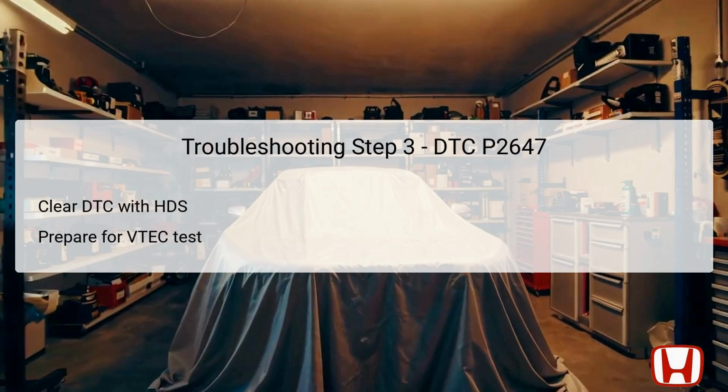Diagnostic System, HDS. Clearing the DTC is essential for resetting the engine monitoring system and creating a clean slate for subsequent tests. It helps ensure that any previously stored codes and data do not interfere with the current diagnostics. After clearing the code, the technician prepares to conduct the VTEC test in the inspection menu, which will assess the functionality of the VTEC system under controlled conditions.